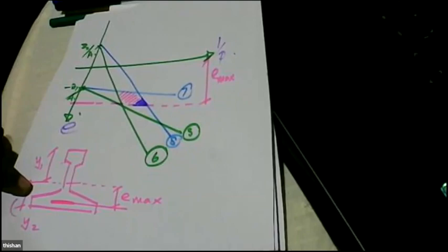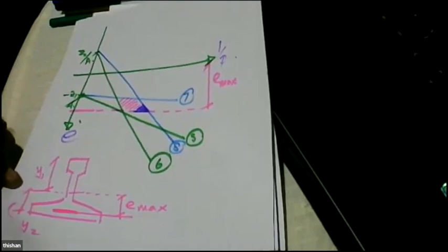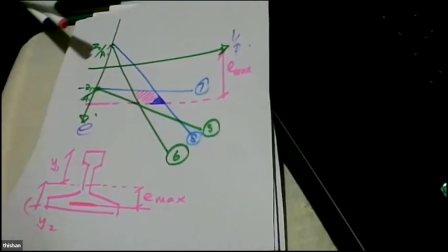So designing a composite beam should not be considered a difficult task. The only problem is it has long equations, much longer than the earlier case. The reason is we are adding so many loads at different levels. First we allow the dead load or the self-weight moment. Then we have to take account of the weight of the concrete that we are pouring later. Then we allow the composite action to develop.